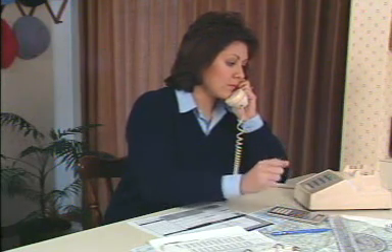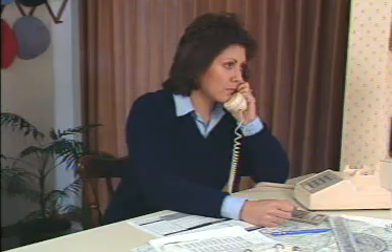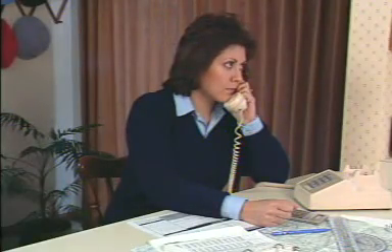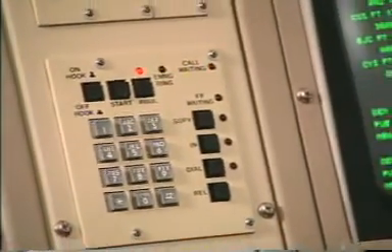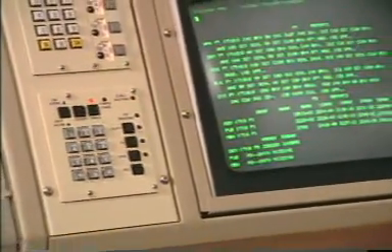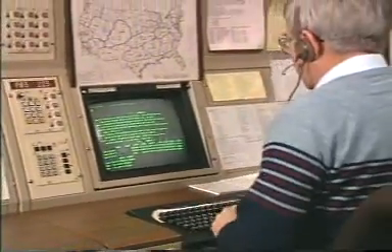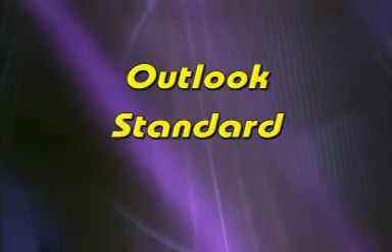You can reach a flight service station on the ground by simply dialing a toll-free number anywhere in the U.S. When you dial 1-800-WX-BRIEF, you will be connected with the FSS nearest your location. The FSS phone system allows you to access a pre-flight weather briefer, along with other services such as FastFile, a flight plan filing tool. When you speak with a pre-flight briefer, you can request one of three types of weather briefings: an Outlook briefing, a standard briefing, and an abbreviated briefing.